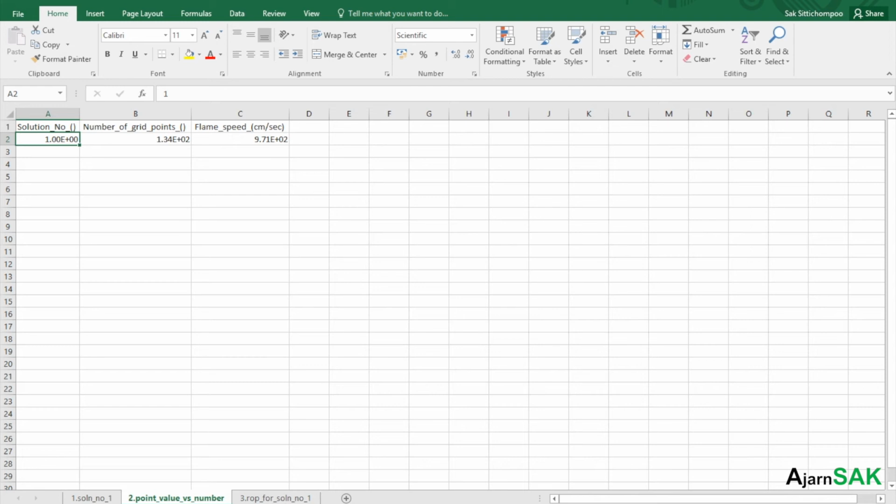The flame speed is like, wow, 9.7 centimeters per second. But it has this E. Oh, yeah, because it's hydrogen. Oh, wait, that would be 971. So at temperature, what was your temperature? 400 degrees Celsius. Your hydrogen flame speed is this much. This is a very correct number. Why? Because at 20 degrees Celsius, it is about 280 centimeters per second. The higher, the faster.